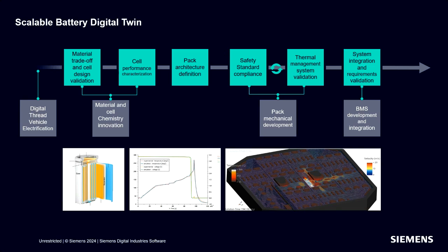We made some adjustments to the number of layers of that battery cell, as well as the thickness. And then we were able to increase the amount of SOC that we were able to achieve, I think to 66% or something like that. And then we were able to apply some preheating and get it to 78%.